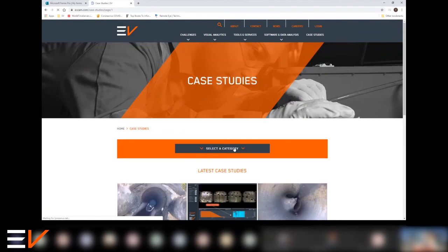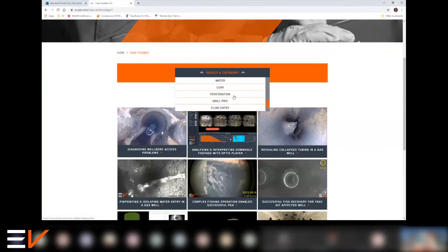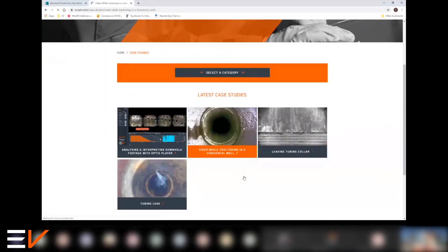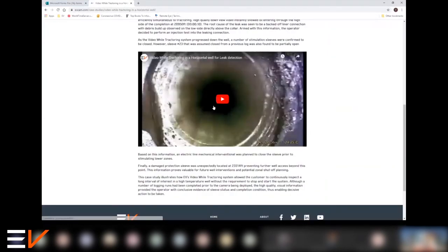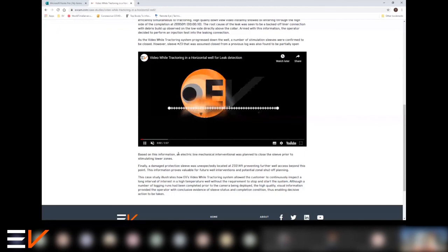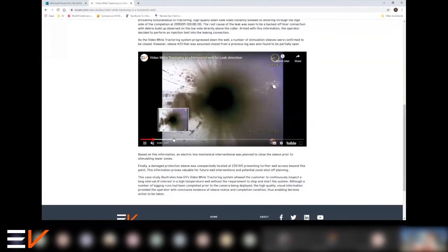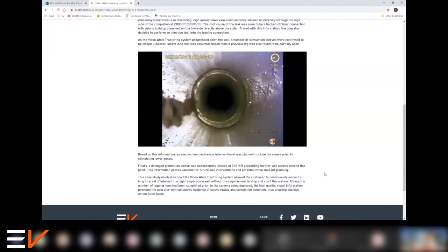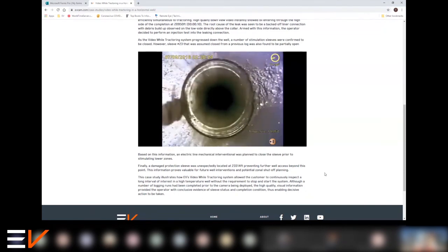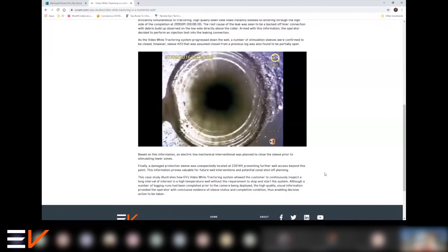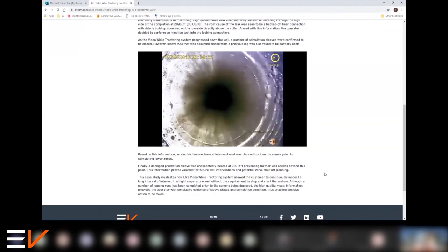There were a couple of other leak examples in there. I think the second one is worth just showing here. This is a much more significant leak that occurred in a horizontal injection well. During a stimulation job, something significant happened downhole. We think there was perhaps a formation movement, and you can see that there's quite a significant leak occurring and some oil flowing on the high side. There's the high side indicator there, top right. This is the top of the well. As we move down the well, we come to this connection, and this one isn't one that has leaked because it hasn't been made up correctly. This one has started to leak because it's been completely torn apart. So again, significant forces downhole to result in that type of event.